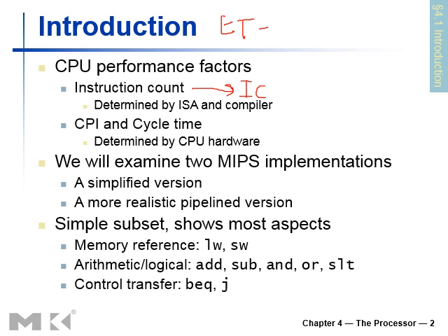was equal to, or we can also call it the CPU time, instruction count multiplied by CPI, that is cycles per instruction, and the whole thing multiplied by the clock cycle time, or divided by the clock frequency of the system. So instruction count is important, and it is determined by the instruction set architecture and compiler. Basically, we discussed what sort of instructions we use to process our task, and what sort of compiler we use to process those instructions.